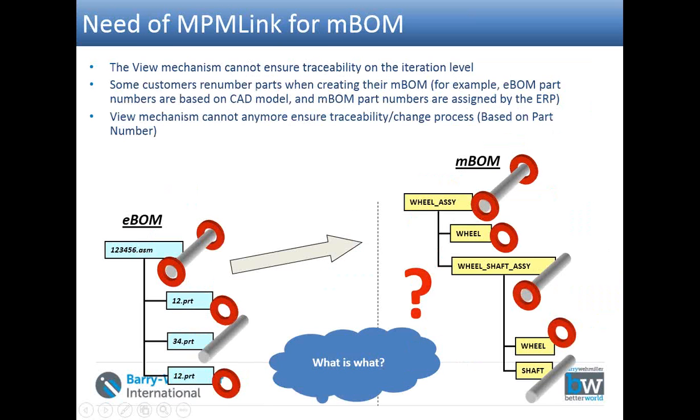So we'll see why we need the PTC Windchill MPMLink for M-BOM creation. As you all know, if you are aware of the E-BOM creation process in Windchill, we have the option called the view mechanism, right? We can still use the view mechanism by creating the M-BOM, but it has a lot of limitations.